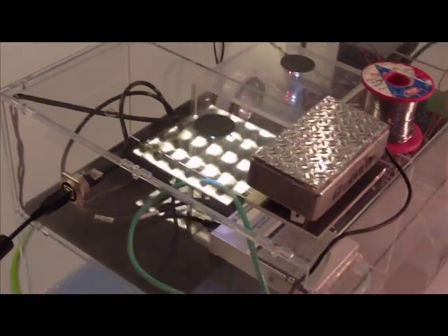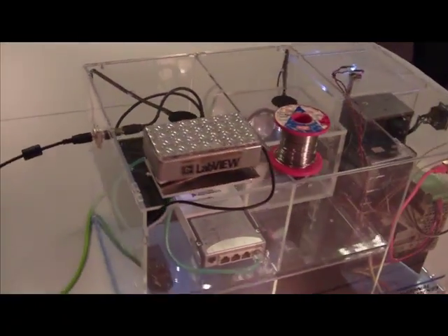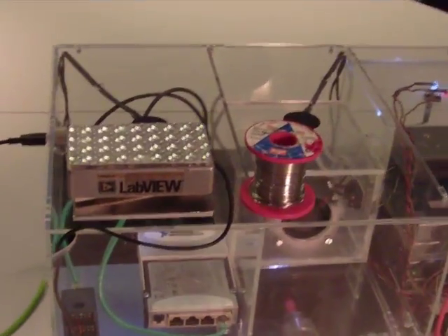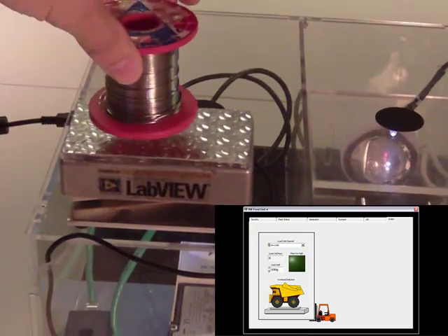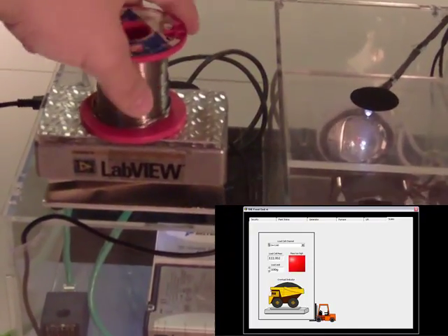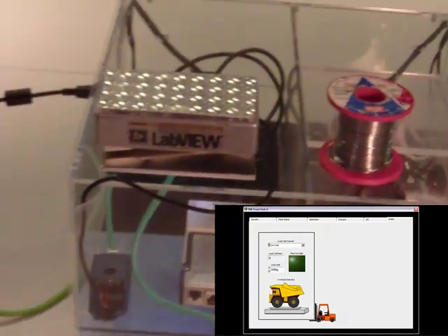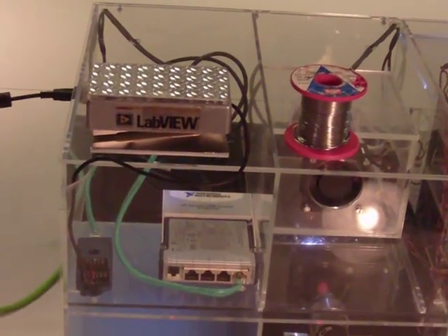The scales were monitored from the host machine running Windows. We used the DAQmx driver and a USB data acquisition device, which included a C-series module. This C-series module was designed for load cell measurements. This measurement could have also been added to the cRIO, however this shows the tight integration between the different platforms.